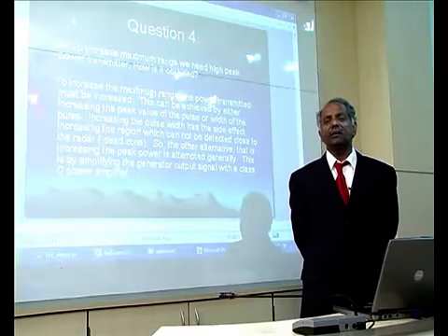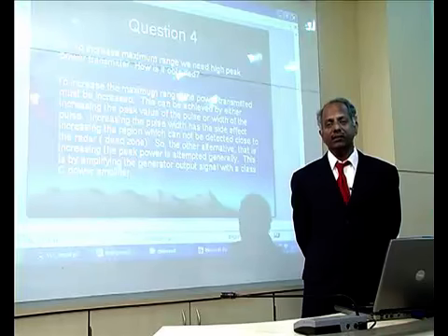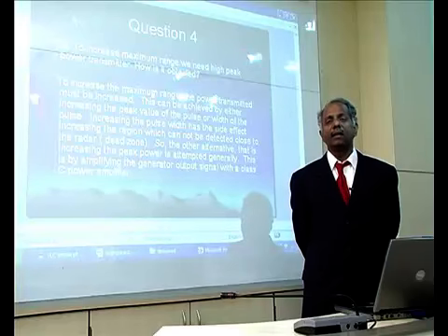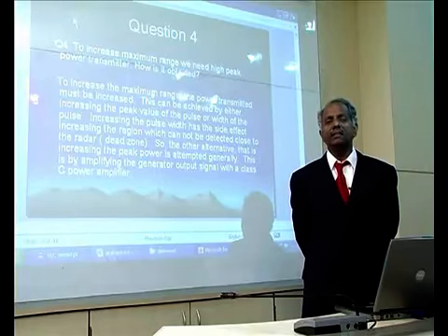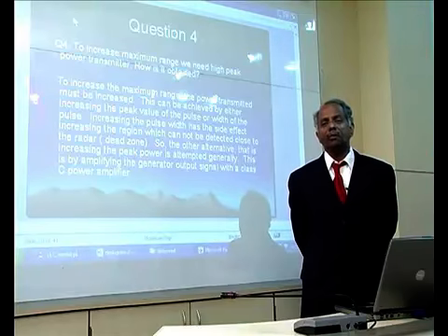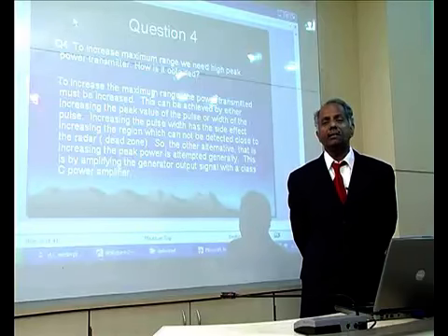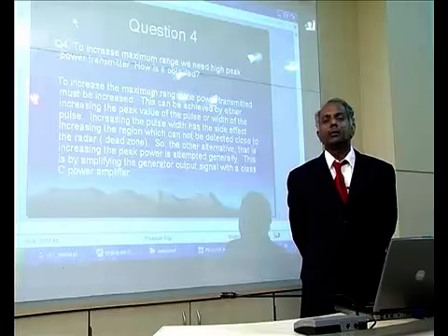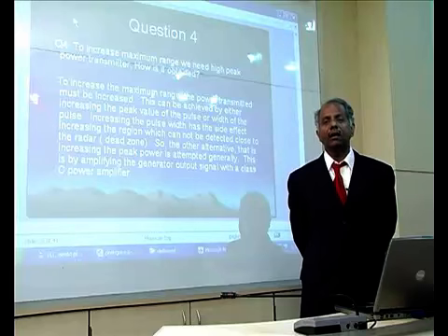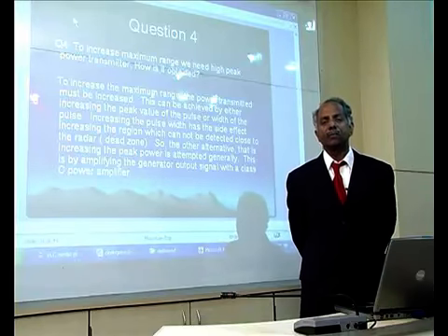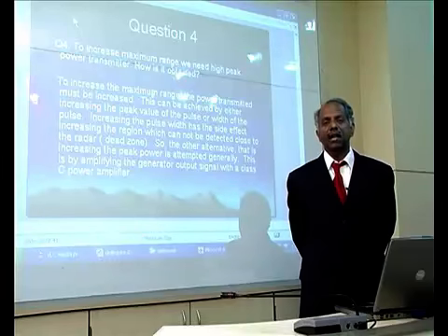If the radar transmitter power falls by 4 times, then the range falls only by half. In this way, there is a direct relationship between the radar range possible and the transmitter power. So, if you want to transmit more power so that we can get more range, the best alternative is to go for good amplification of the signal after the modulation. And here we employ power amplifiers to amplify the signal to be transmitted.